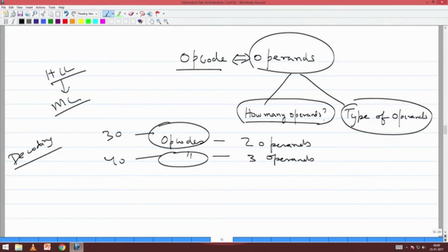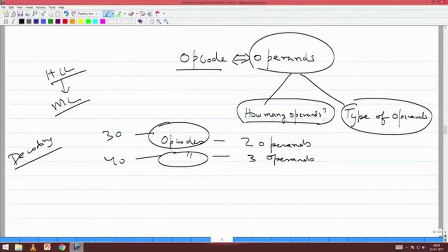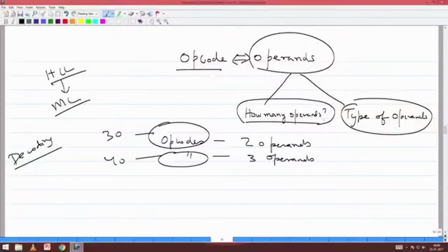There are ones and zeros coming into your hardware, and the hardware should understand, yes, I have to do add on this, subtract on this. So there is an implicit understanding happening within the hardware, and the hardware should realize what is the opcode and what are the operands. That is also a part of the understanding process. Now if I can interpret my opcode and the operands concurrently, then my understanding process becomes faster.